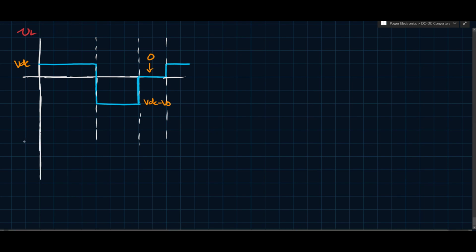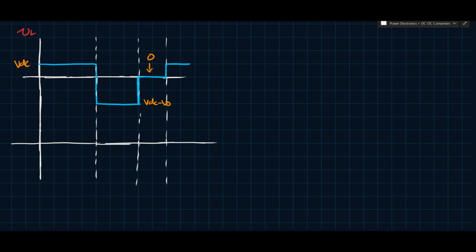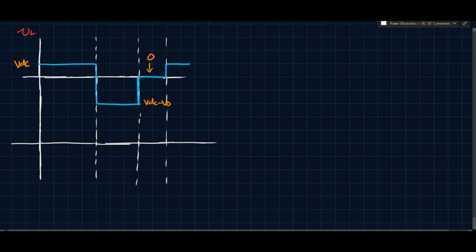Now, the current. This is the more important thing, I guess, because it is more indicative of the two, since the conduction mode is, after all, defined in terms of what the inductor current is doing. So then there'll be a 0 time.